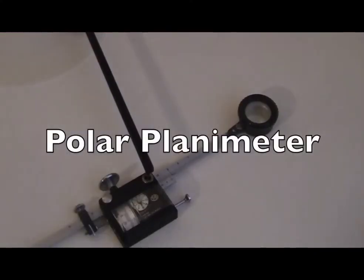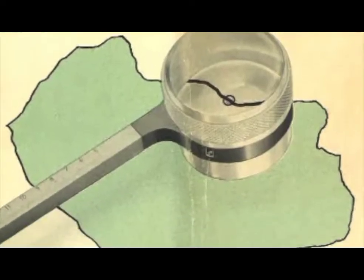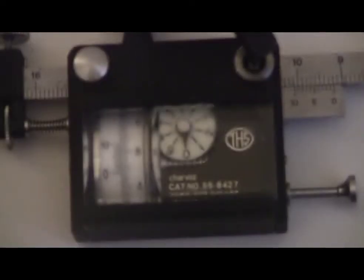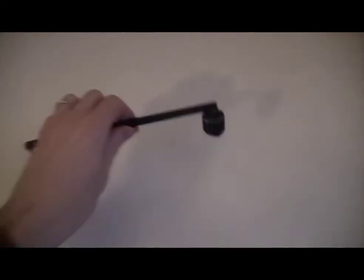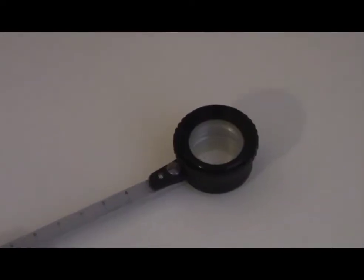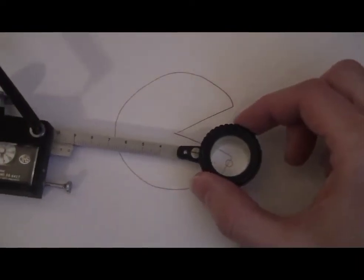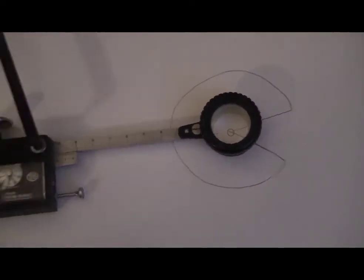This is a polar planimeter, probably from the 1960s. Actually, it's a THS Charvaz compensating polar planimeter with zero set device. With the original case. It's got two arms. The weighted arm that stays put, and the tracing arm with the roller on the bottom that moves around. This is the tracing lens, which has a little bullseye. You trace around the edge of a shape, and the dial tells you the area.